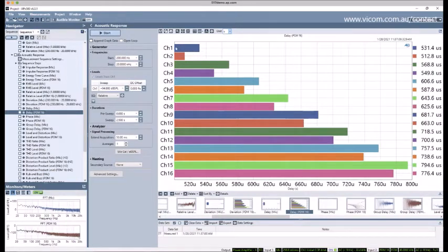So the data line for microphone number 1 is actually reversed with its paired microphone in MEMS. In the typical PDM signaling scheme, every one data line is shared between 2 microphones. So you can see this little ripple through of the inversion. So it's actually, so the physical microphone number 1, its data is actually coming through on channel 2.